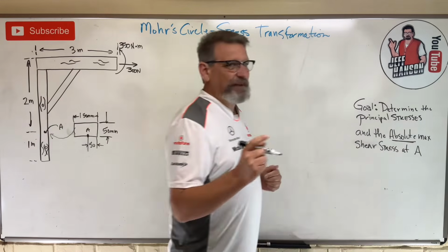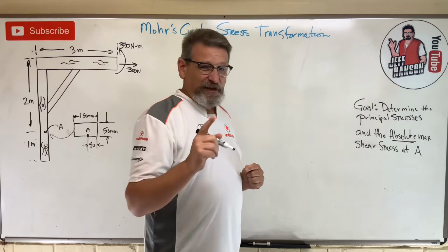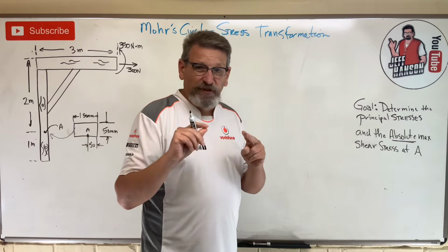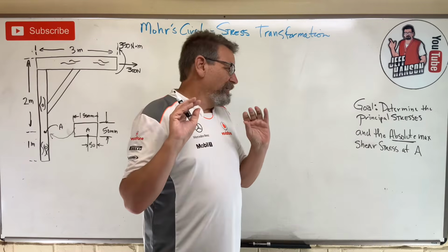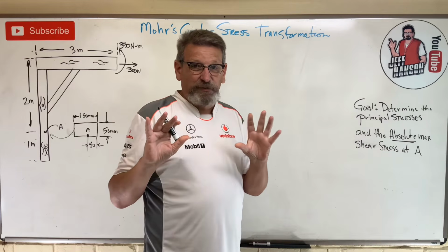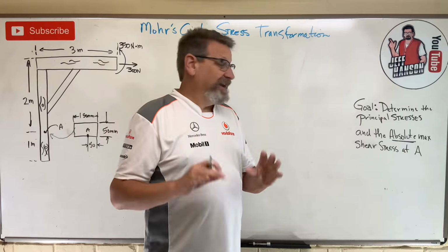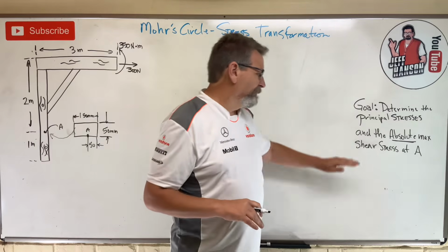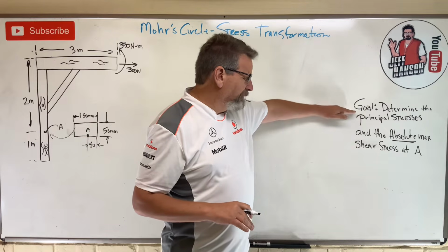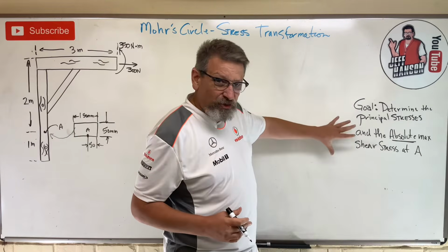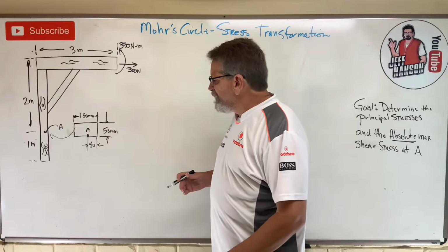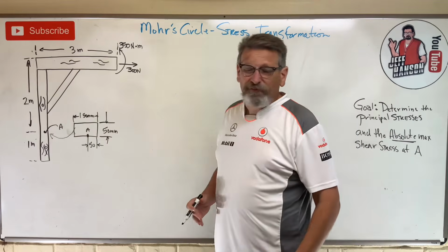And if you don't understand that absolute, check out the next video, I think it's 2 videos away. It says how to find absolute shear stress. That's a really good definition and explanation of what that is. But we're going to find it here as well. So find the principal stresses and the shear stress at point A. That sounds like more circle kind of stuff. But in order to find that, we got to do the combined load.